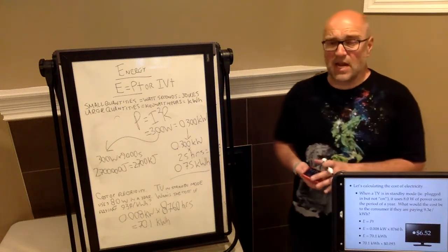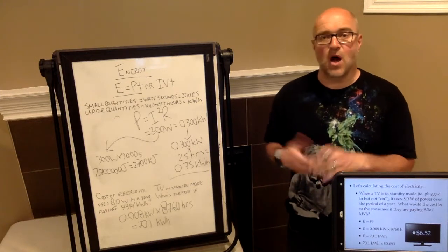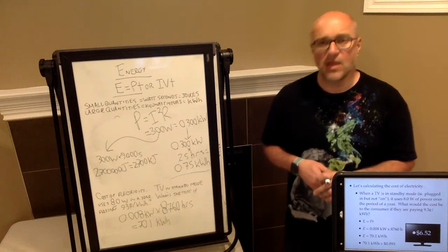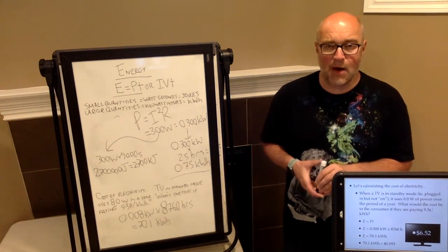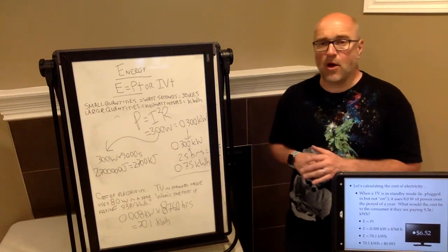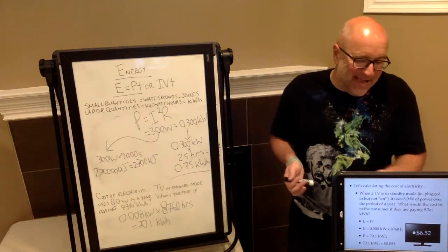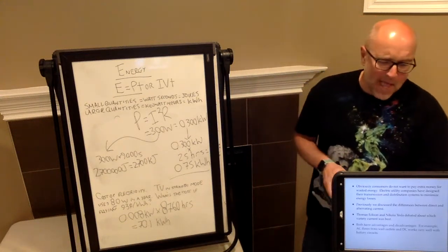So that's how you calculate an energy bill based on knowing the power of the device and how long it's been on. You find out how much energy it's using in kilowatt hours, figure out the rate per kilowatt hour, and then just multiply by the rate per kilowatt hour, and you got yourself your power bill, or your energy bill, because it's not a power bill. I keep saying that because, hey man, it's entrenched in this old brain of mine.